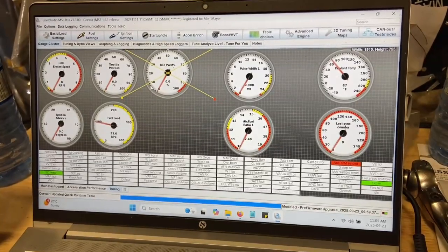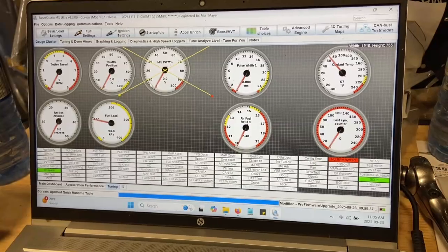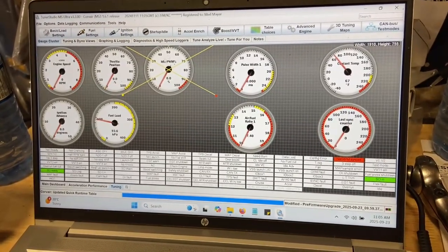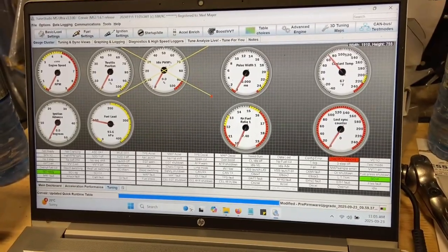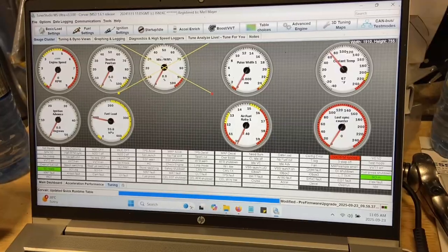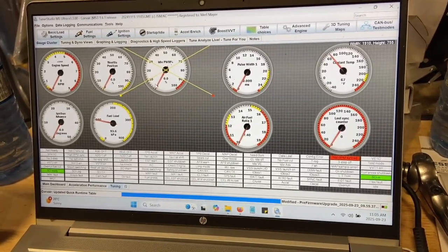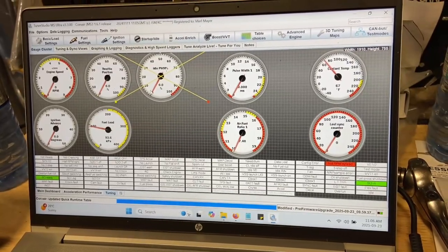You know, probably under 10 when I'm sitting there running warm at my preferred idle, so that when I go for a drive and I'm coming back down to idle, the IAC can hold it open and tail me down. So if I do a burnout, I can actually have this come down slowly instead of stalling when you get out of doing a burnout. In this car, I'm not doing a burnout, but in race cars and stuff like that, that's one of the things.